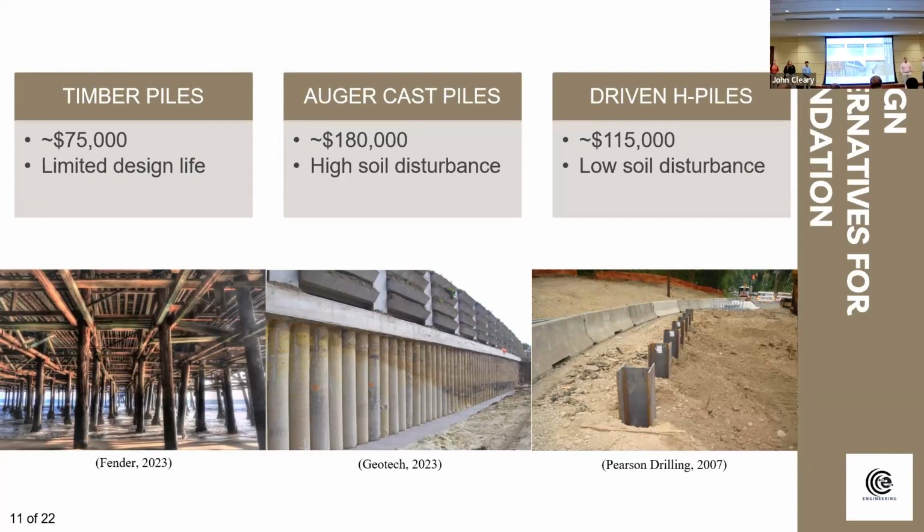How did you determine the height and the length of the bridge? So actually, we determined the height based on the HEC-RAS modeling. Currently the bridge deck is 15 feet above the creek bed, and it experiences flooding whenever there's 4 or more inches of rainfall. So basically we just modeled that in HEC-RAS and raised it according to that, and according to the 100-year storm, which was the highest thing possible.